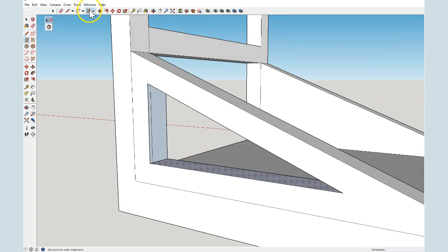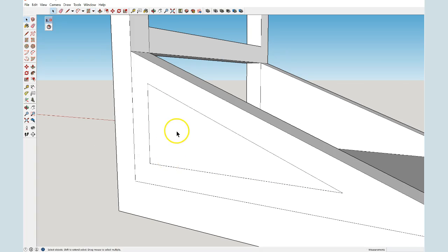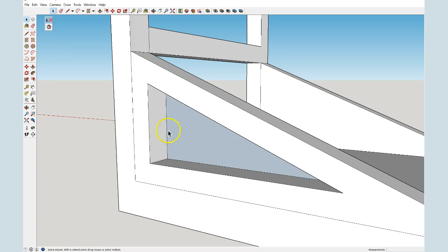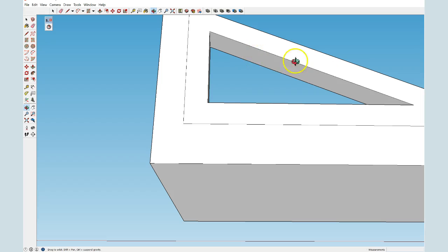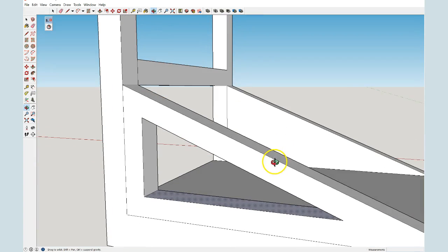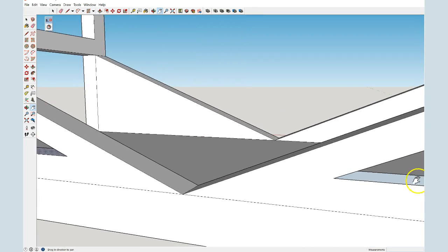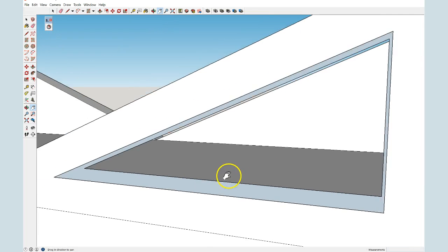Select the rectangle, and I'll go from opposite corners. So that corner to that corner. And then I'll delete the center again. I'll delete that center. Okay, and so you can see now we have an edge right there. We have an edge right there. And it also put an edge on the top for us. And so now that fixes that problem, and then we can do the same thing over here.